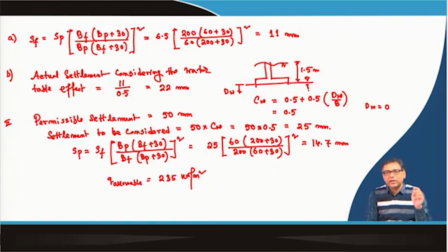How you will use the depth correction, I have already discussed during my settlement calculation part, but I will also show it in one of the example problems in this or the next classes. Then you have to apply that depth correction in this settlement value. Okay. And the difference of the depth will be your depth of foundation in such a case. Your difference of the depth between the plate and the real foundation will be the depth of foundation.